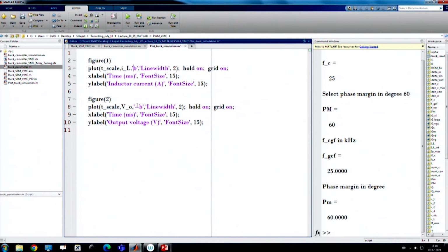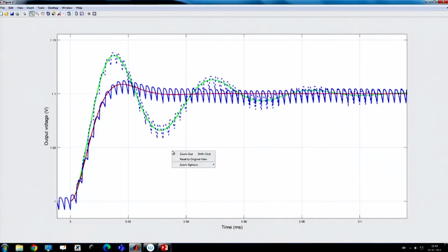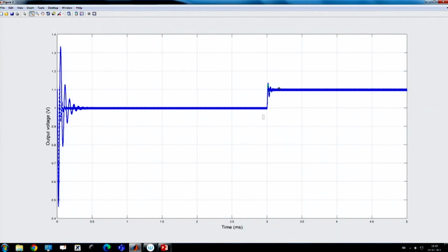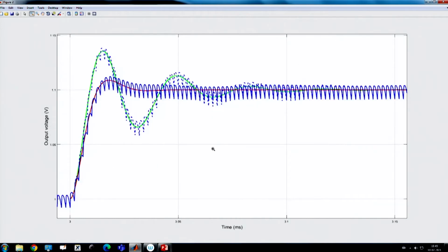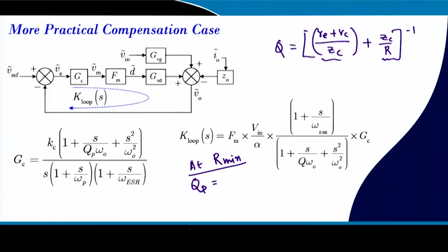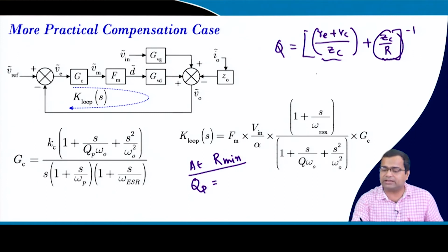So here we are compensating using, yes. So, here it looks like if we use the minimum value of load resistance, it may not be a good solution at light load, because at light load this term is very low, and it is dominated by this other term.